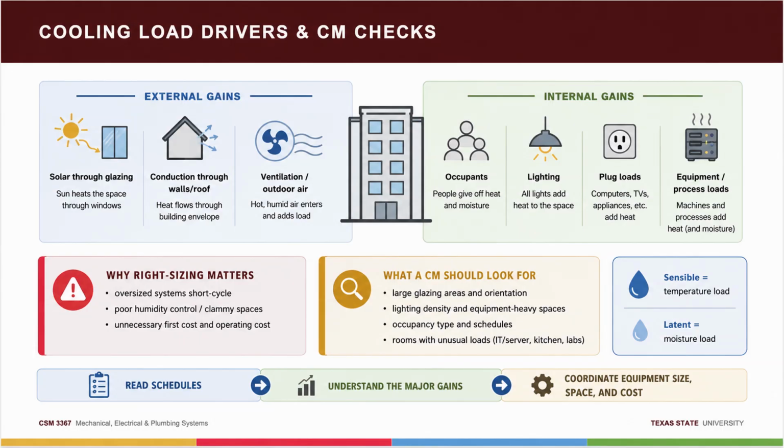All watts, no water. Which, file this away, is why data center cooling is a completely different design problem than comfort cooling. An open door to the loading dock in July. Both. That's infiltration, and infiltration carries whatever the outside air carries. Good. If you can sort any source into its bucket like that, you've got the vocabulary. Now let's start counting the BTUs.